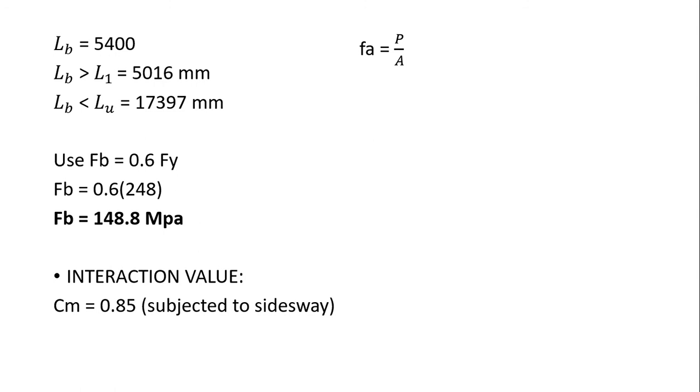So, the actual stress is P over A. So, substitute the value of the load, which is 1,784,000 over 29,999.94. So the actual stress is equals to 59.47 MPa.